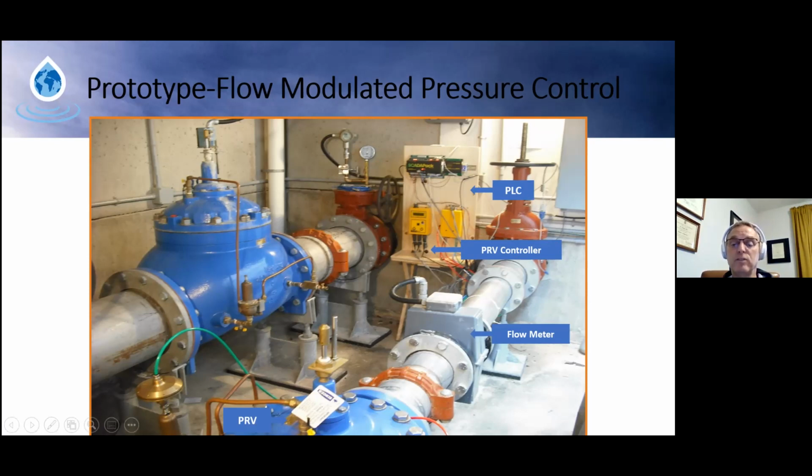This is the domestic flow. And just so you know, this is for fire flow. So if something happens, there's a huge fire and it calls for more water, this detector check valve will open up and all kinds of water will flow, and that's all good. And the fire will be hopefully controlled by that huge amount of water. But during most of the time, we have domestic water flowing through here. We do pressure reduce, and here's the PRV you see there in the foreground. Okay, I can even read the tag.